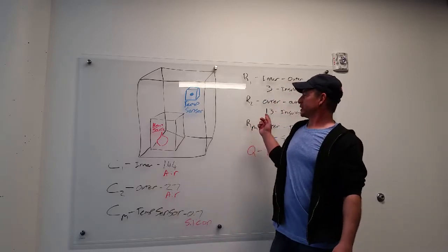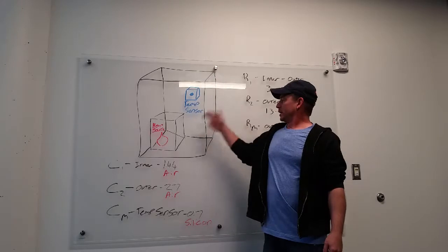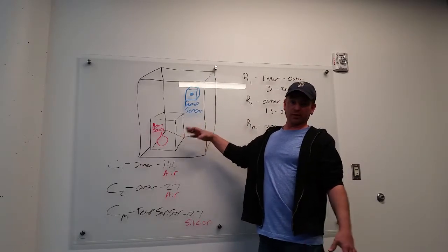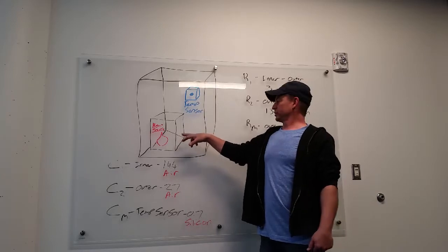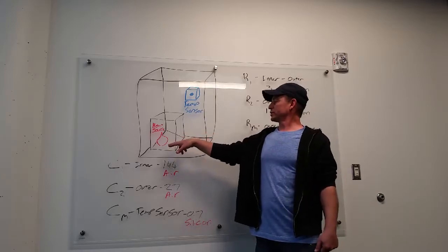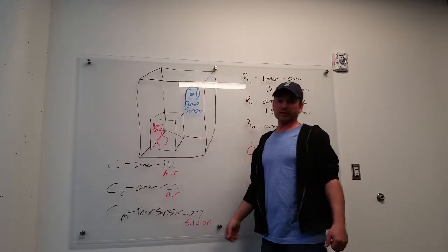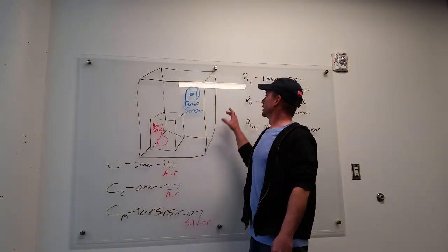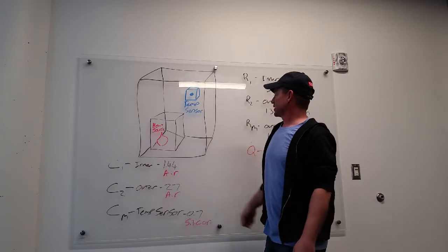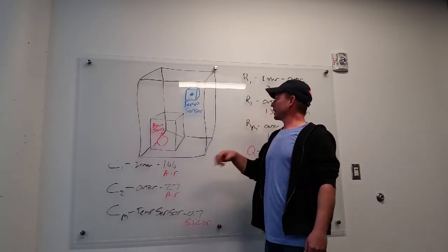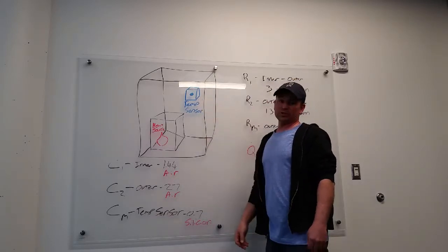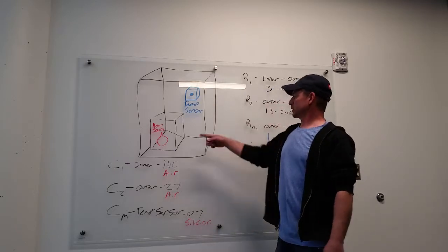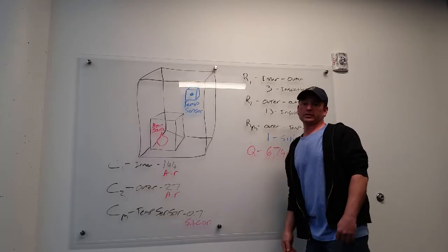So what we have is basically a hot box that needs to be at a higher temperature for doing some curing, and the heat source, which is a kerosene lantern, is inside of the hot box. This is a basic representation of the outer shed, and then a temperature sensor inside to turn the heater on and off.